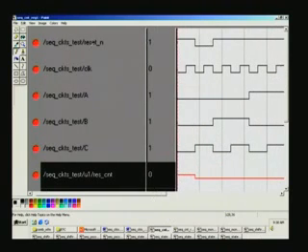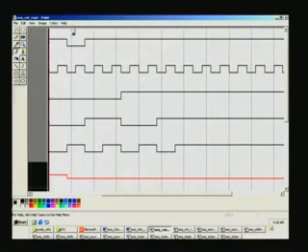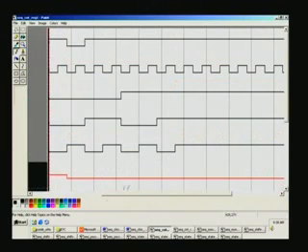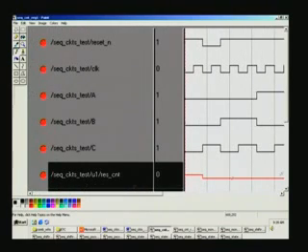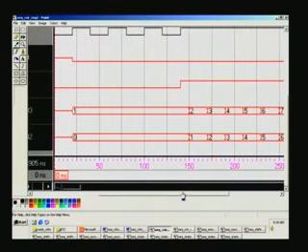So you can see reset, clock, ABC are the inputs, and the first one is reset count here. You can just have a look here, and with the reset, this counter edge is cleared right at that point of time. The last one is counter edge, and you can see the time axis clearly here, 50 nanosecond and so on. So it is around, I think, 20 nanosecond that it goes to 0, and that's what we had put in the test bench. And here it starts incrementing only at this edge.